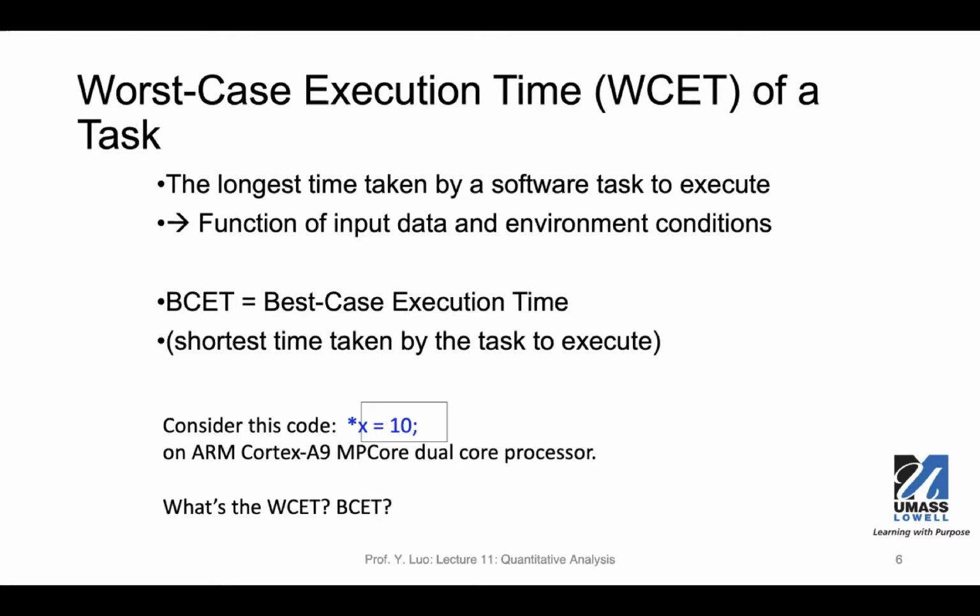Also, writing to this variable will cause a write access to the cache, which has to write back this new value to the memory. That will also be a variation in the total execution time. So it's going to be very hard to exactly pinpoint the execution time for this particular instruction.